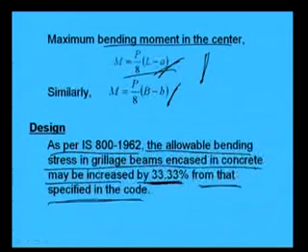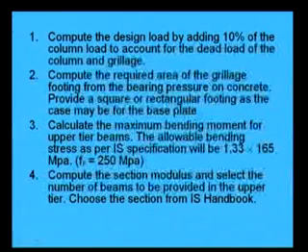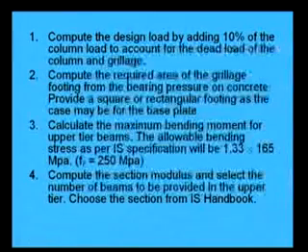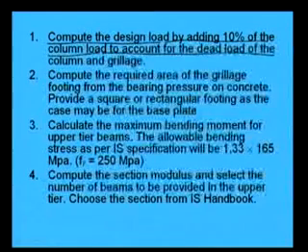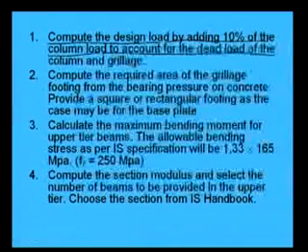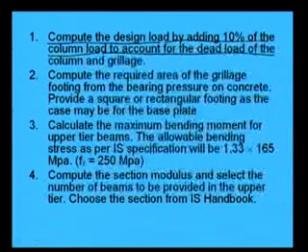This is one thing. So, what we will do is compute the design load by adding 10% of the column load to account for the dead load of the column and grillage. So, whatever load is coming, we will add 10% more due to the self weight of the grillage and the plate, etc.